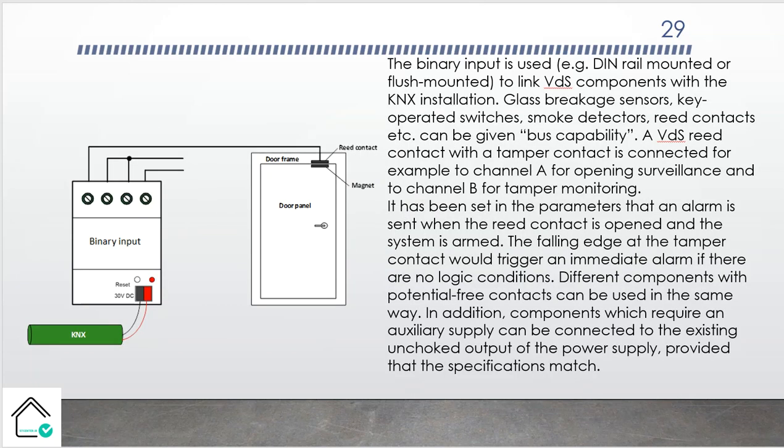But we need the binary input to connect it to the conventional sensor or VDS sensor, okay? And the important thing is this binary input should show us any penetration. In some cases you should use the resistance. And then if somebody cuts the wire, the resistance changes in the loop, and the binary input provides us some sabotage or penetration group object information.